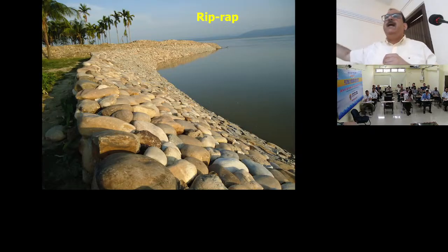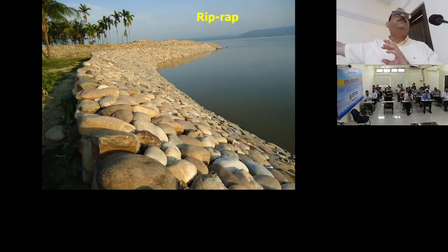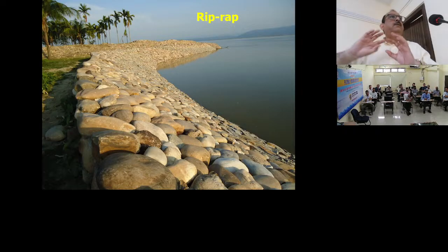River boulders should never be used in protection works. I should say rounded boulders should never be used in protection works, because they will escape. They will roll and then go to the river. They will not stay in the bank.